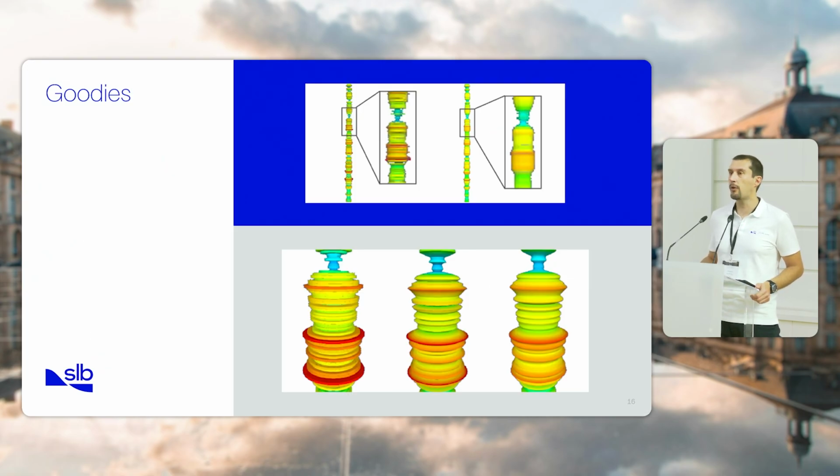There are also some goodies that weren't anticipated at the beginning of the development. If we just enable MIP mapping on the log values texture, which is a 1D texture, we directly have a MIP mapping mechanism on the color, but also on the shape, on the surface. And if we change the interpolation of the texture, from nearest to linear or cubic, as in the picture at the bottom, the algorithm directly adapts to the interpolation without the need to regenerate anything. As it just takes the values, it directly uses the interpolation which is currently configured.